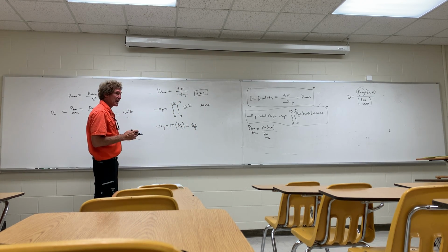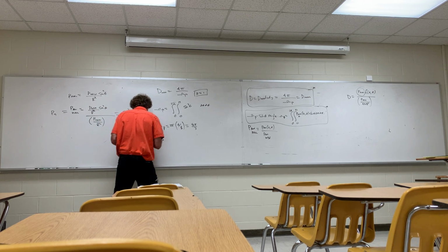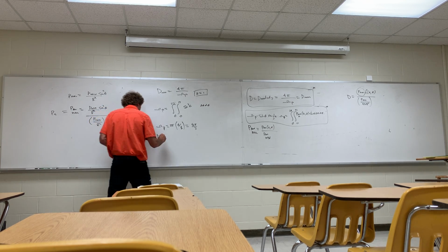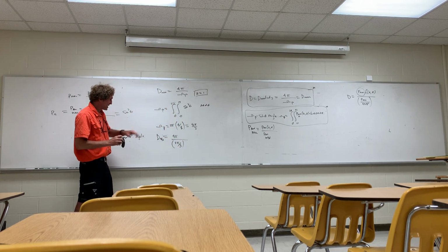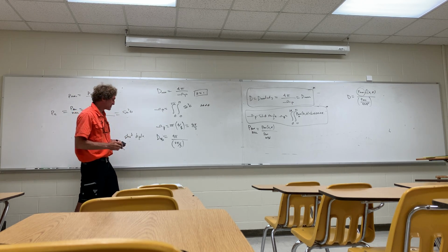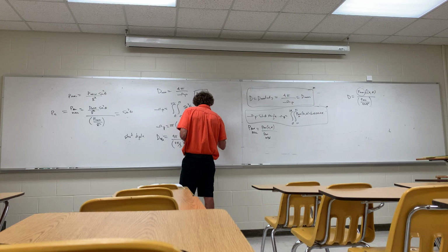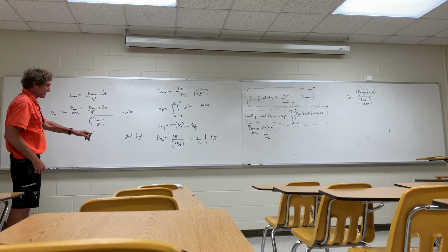So when we have a short dipole, when we look at the maximum value of directivity, D max, and this would be for a short dipole, that's going to be equal to 4 pi over quantity 8 pi divided by 3. I'm just taking this value, plugging it into the definition I've showed you. And this is going to be what? 3 halves, or 1.5. And that is the maximum directivity. Now I'm just going to finish up here. Y'all with me on that?